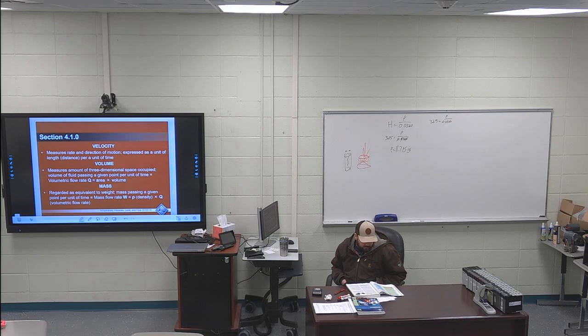Multi-phase flow, I have highlighted. The simultaneous flow of materials that have different states or phases, solid, liquid, or gas, or have different chemical properties for the same state, for example, oil droplets in water. Primary phase is a continuous flow, the secondary phase are dispersed within the continuous flow.